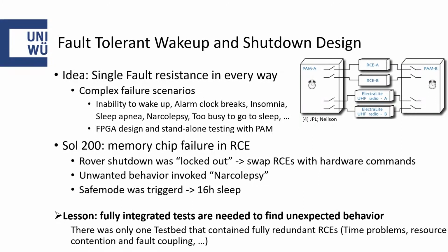On SOL 200, something very bad happened. A memory chip failure in the RCE. The rover was stuck in the shutdown procedure as a line wanted to be read out of the memory chip but could not, and therefore it was stuck in an endless loop in the logout procedure and could not shut down. And that was very bad.